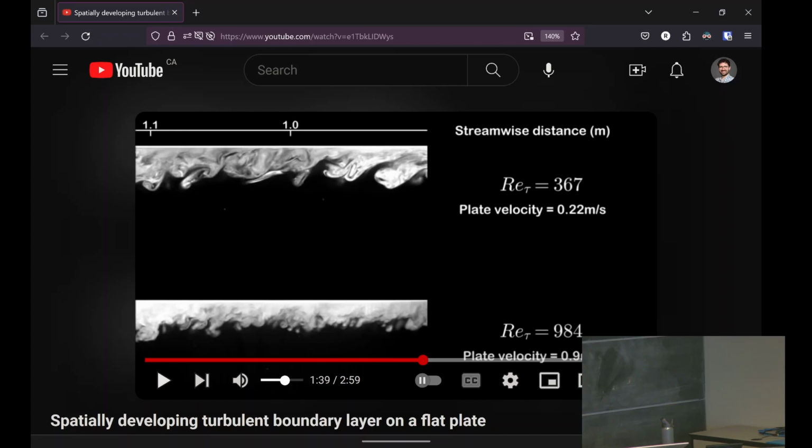Like I said last time, if we had Couette flow every time we put something in a fluid, then a lot of fluid mechanics people would be out of business, because this is what keeps us in business most of the time. This is quite complex, but this is what creates drag on airplanes, for example. So we have to understand this. Yep. So you just said that as we increase Reynolds number, the boundary layer gets thinner. Yep. The last graph you showed, increasing Reynolds number, that's for a fixed x. So for a fixed x location, if you increase the Reynolds number, your boundary layer will be thinner. So the plot that I showed was sort of for a growth along.